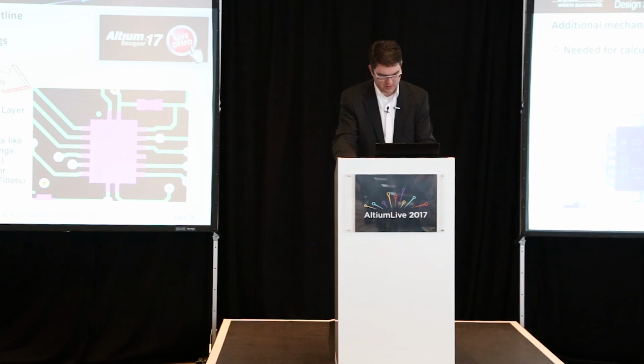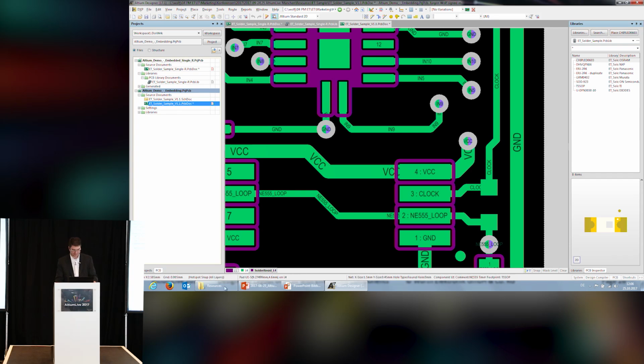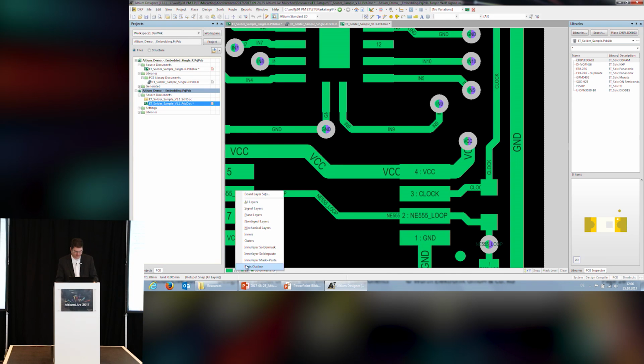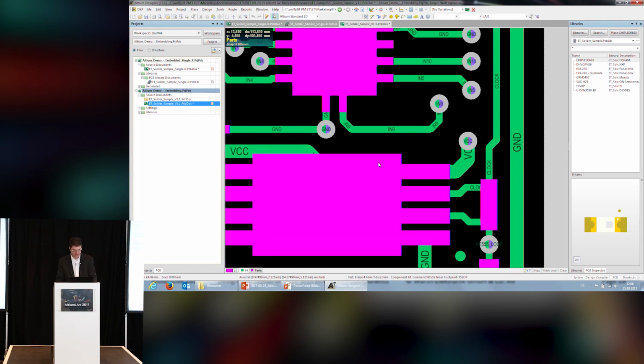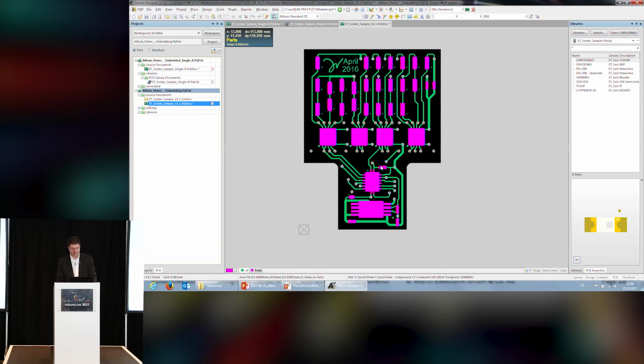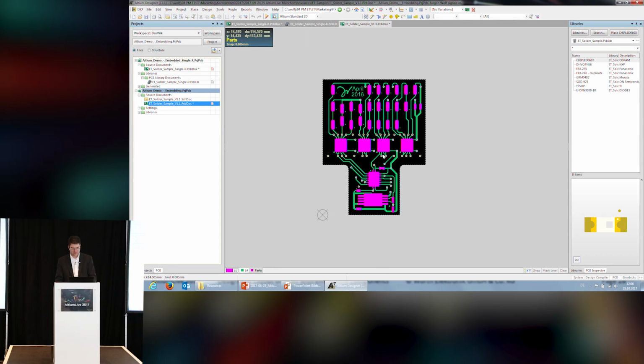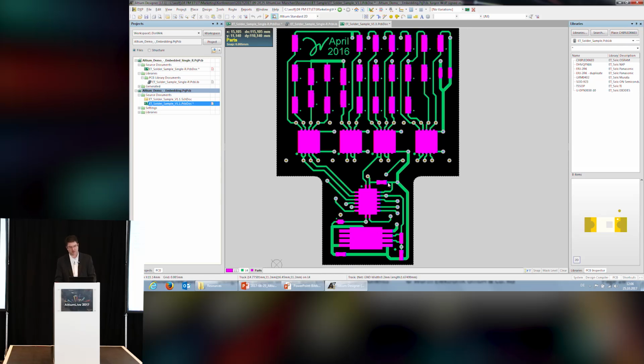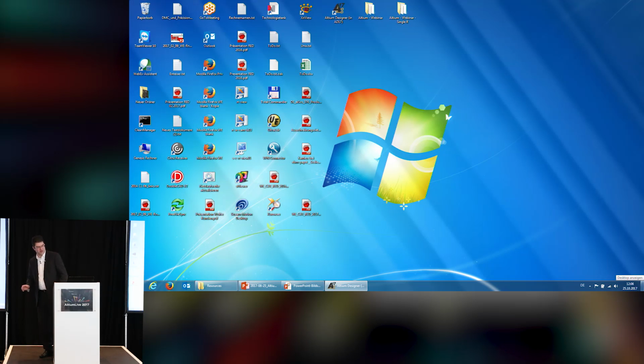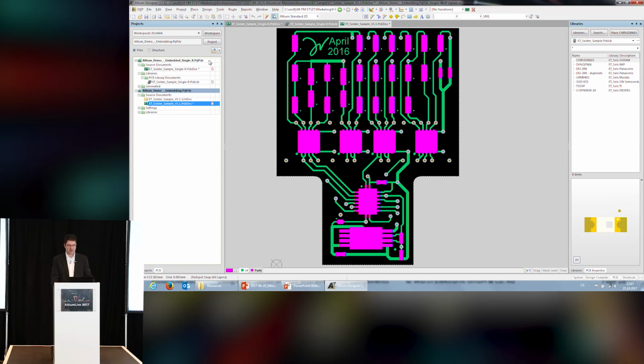Again, in Altium, switching back, this is what I've done in this next few parts outline. So this is what it actually looks like afterwards. We see the parts with all their joints and so on, and if we take this and put it onto a big panel, we actually see how we can group this stuff, and our CAM engineers can work with that one. It's always the max tolerance. We always calculate with the max tolerance of the components.